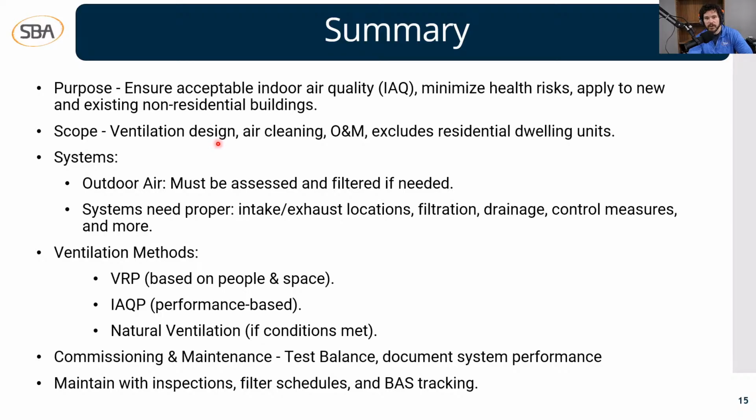Now again, we talked about this last week as well. This excludes residential dwelling units. That's 62.2. So now for our systems, the outdoor air must be assessed and filtered if needed. The systems need proper intake and exhaust locations, filtration, drainage, control measures, and a bunch more.